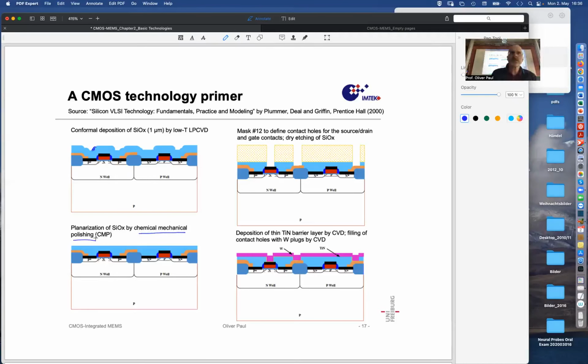These are machines that look pretty dirty. It could be considered a dirty process. You have these machines with some felt pads, some slurry, cerium oxide microparticles suspended in a liquid, and then comes the wafer, and the wafer is scraped over that slurry, and material is removed. And if the pressure is right, and the speed is right, and the combination of slurry and material is right, only the top parts will be removed.